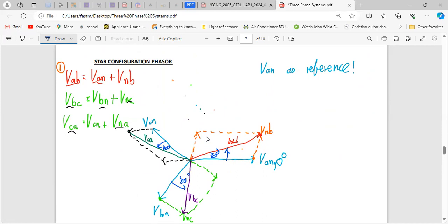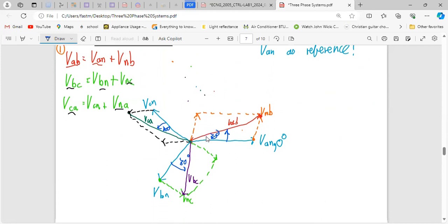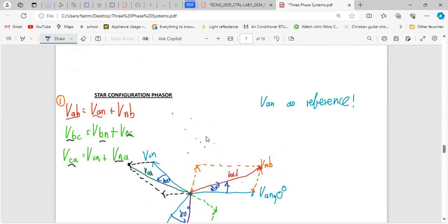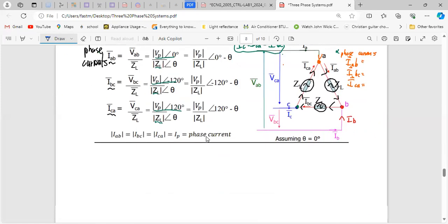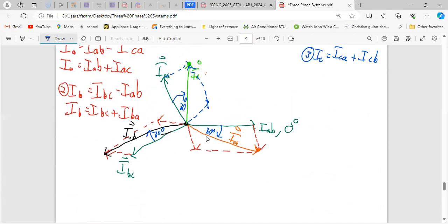Right? So you're saying that the phase and the line are opposite. So therefore, your line is leading the phase. Yeah. Because if they also do a race, this will win. He will be behind. Right? And then for the delta it's the opposite, it's underneath. Yeah. So IAB will win in a race because IA is behind. Yeah. So that's how you know what is leading and lagging.